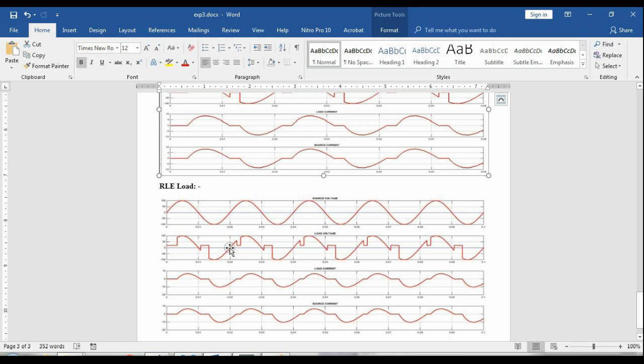Here the inductor current is not 0, so it goes to the upper part also, and as soon as it reaches this point, the inductor current is 0 and it must return to its original state, that is V0 equal to E. Again here we trigger, and the waveform will follow the source voltage.